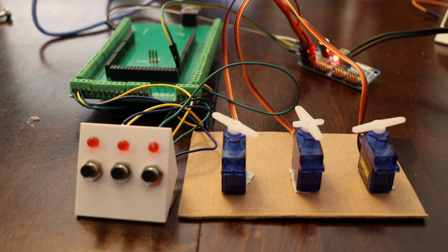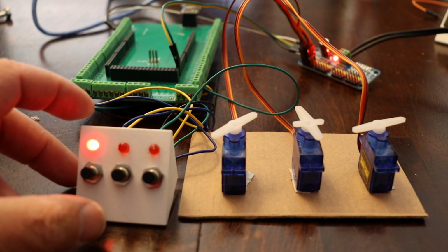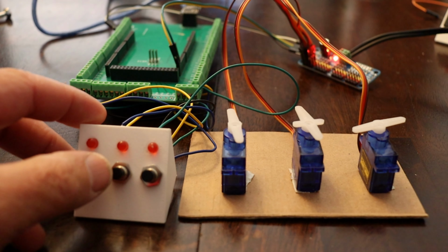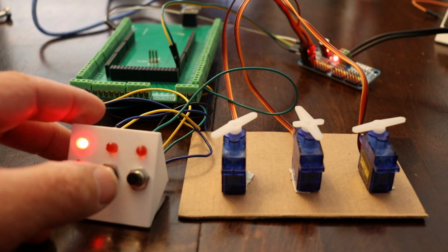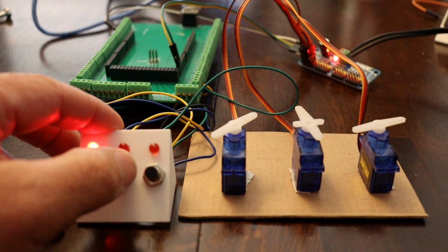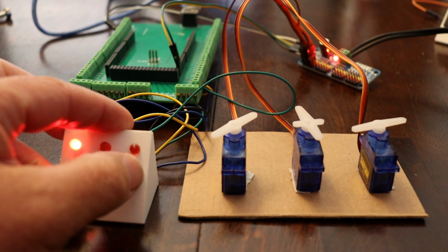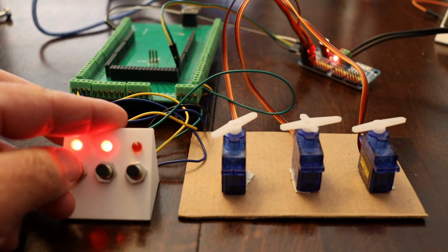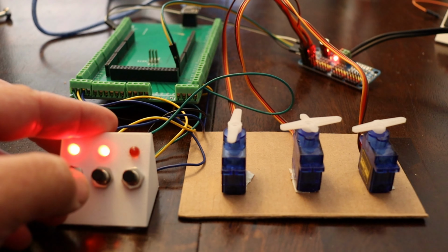Okay, just talking about the delay we put in for pushing the momentary switches. I've actually gone back and removed that delay just to kind of show you why you want it, what happens if you don't have it. So if you remember, when you're pushing a momentary switch, it's constantly reading it, so you can kind of see how things are twittering around, and it gets confused, because even just trying to press the button, your finger doesn't move fast enough to stop it. So you need just a little bit of delay on those buttons to make it work smoothly.